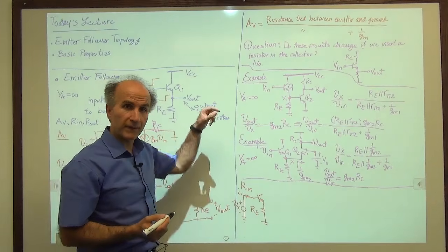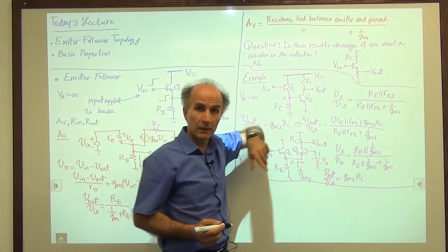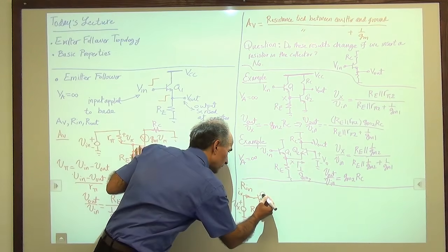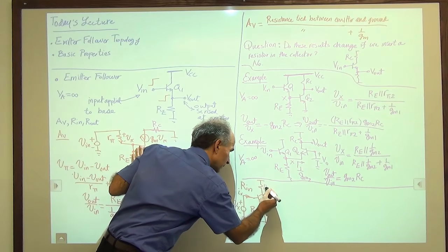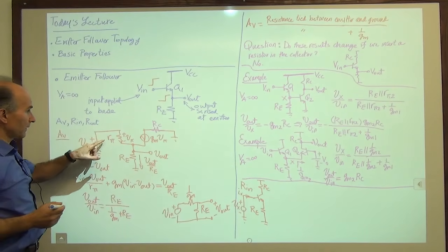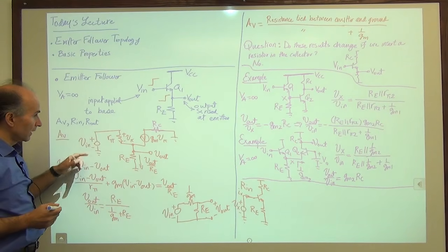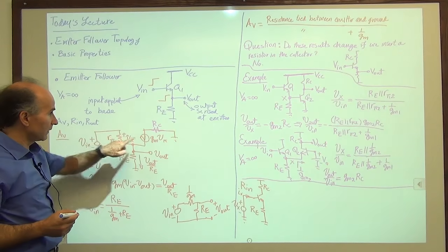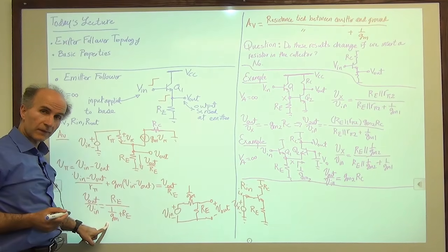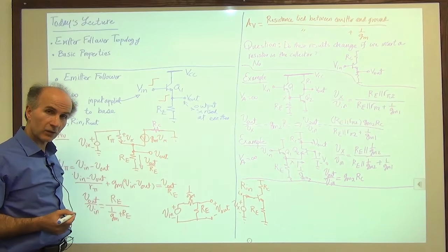Okay, now remember what we just said. We said whether we have a resistor in the collector or not, this circuit doesn't feel it. So does it matter if I add a resistor here? No, because you can again think about it this way. I'm interested in this current, right? V in over I in, or Vx over Ix, would be the input resistance. Now, does this current get affected whether we have RC here or not? No, because none of the equations that we wrote here changes, right? So I in doesn't change, V in over I in or Vx over Ix doesn't change.